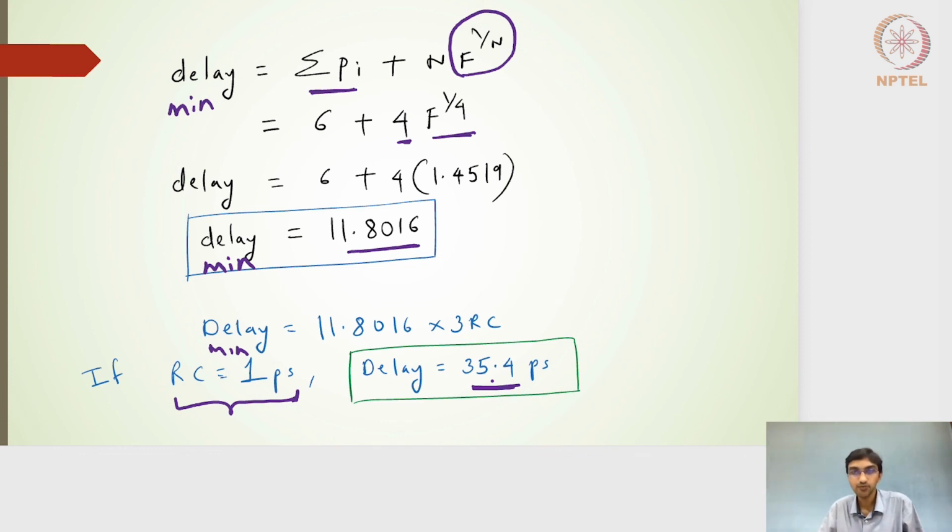So in this particular lecture, we started with understanding the gate sizes and how they are distributed to the individual transistor sizing, the widths of the transistors, especially on the PMOS and NMOS sides for different gates.